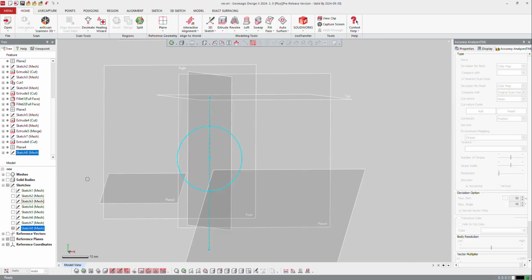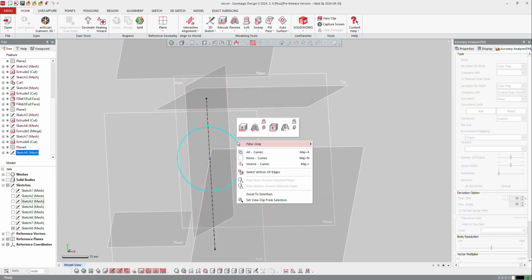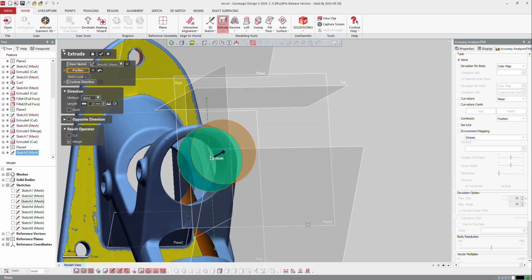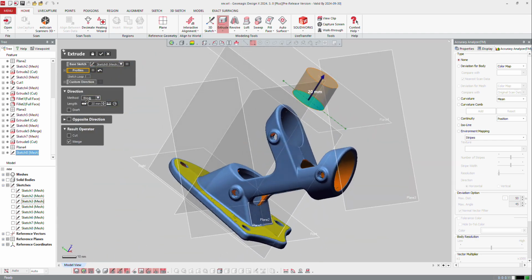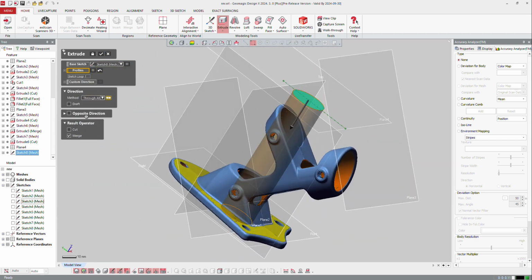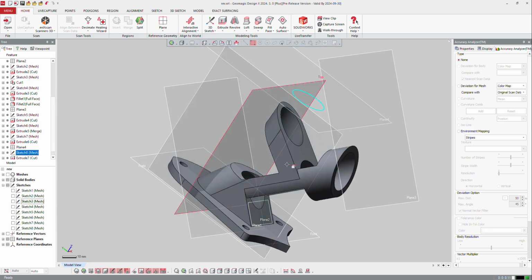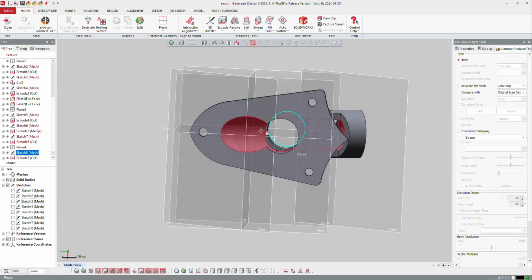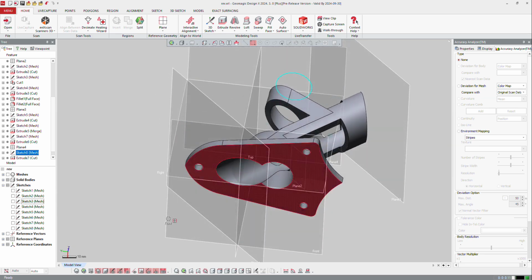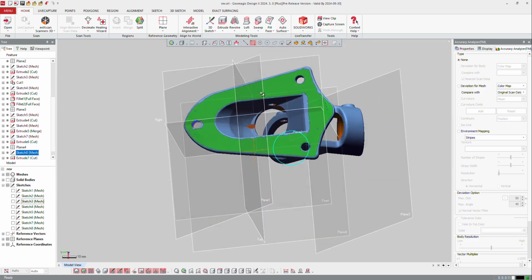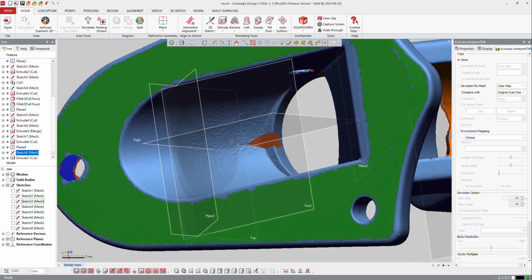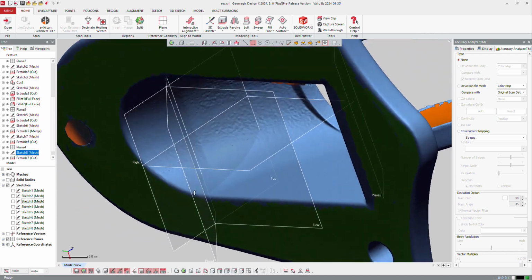Then you can exit the sketch, and again, as before, extrude in solid, and of course, display the model, reverse direction, and through all, and of course, cut. And all right. Now you can display your part, and what you can see there is that it's not the right shape you get there. So if I look at the mesh, here it's just a standard opening with a full face fillet maybe there, so you can display that afterwards.